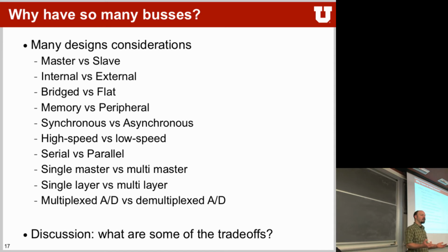Now, if you want to push that out of the chip, you need 64 I/O lines hooking up to it. And that's not all, especially not in the AHB case. The AHB, I think, has about 128 different lines that go back and forth to make stuff really fast, right? But as soon as you go external, you want to reduce the number of pins that you have. Make sense? So that's some of the big trade-offs that you have.